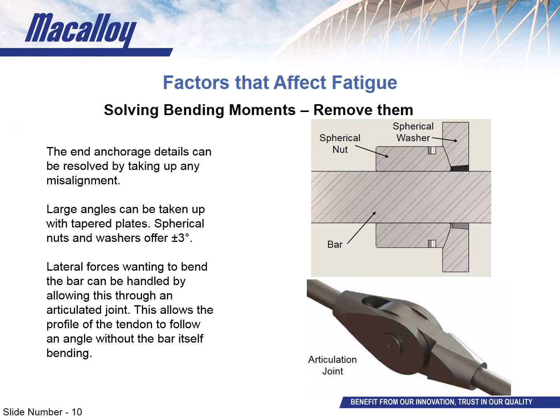With the use of the aforementioned connections, the area that experienced the bending stress in a standard system no longer has that additional source of stress. This reduces peak stress and stress range, thus improving the fatigue life of the system.